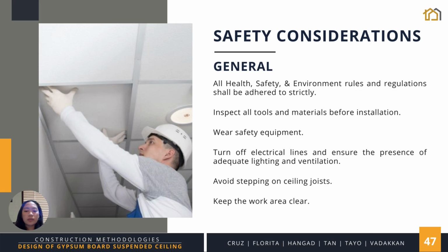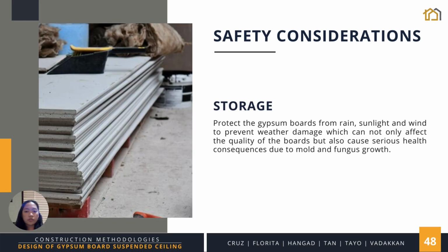Next, avoid stepping on ceiling joists and use ladders instead to avoid risks of falling or other injuries. Lastly, the work area should be clear of debris, tools, and other unnecessary objects to avoid stepping on them and tripping. The gypsum boards must be stored in rooms with good condition.